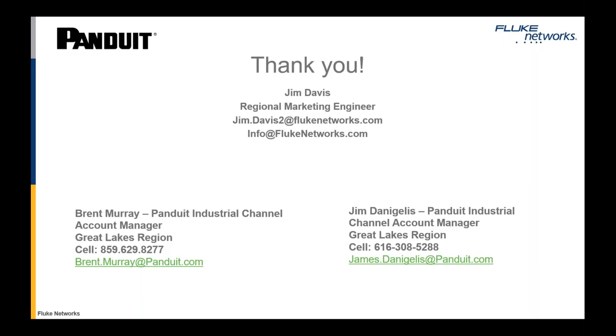Thanks, Jim. Our next question is, what is the difference between M12 X code and D code? Yeah, I can take that, Jane. So the difference between the D code and the X code, they're both Ethernet cables and they both use Ethernet connectors. The D code has been around for a lot longer time frame, and it has a different number of pairs.